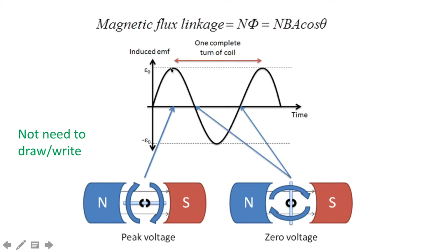So here we have the EMF being at its maximum. When the coil is upright, as seen in the bottom right diagram, the field lines lie in the plane of the coil. There is no change in the magnetic flux, and the EMF is zero, as you can see on the graph at these 2 points. And this is because the coil is not cutting across the field lines.